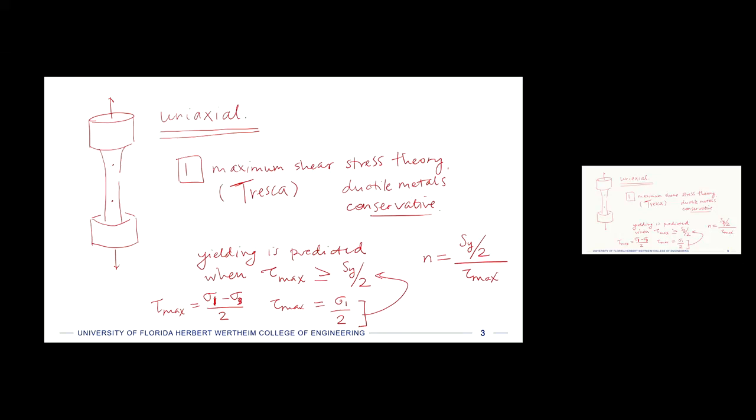What we measured should be, if it's a maximum stress we're applying to something, not as high as the failure criterion. So that means if n is greater than or equal to 1, we would predict safety, or no yielding. You know from experience, factors of safety are often 2 or higher, but this is what we call a factor of safety.